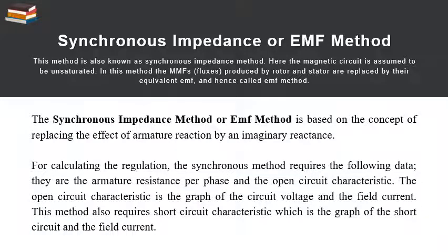The synchronous impedance method or EMF method is based on the concept of replacing the effect of armature reaction by an imaginary reactance. For calculating the regulation, the synchronous impedance method requires the following data. They are the armature resistance per phase and the open circuit characteristics.